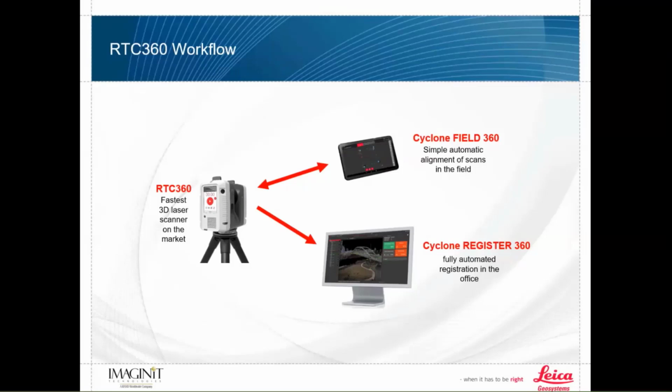From the RTC, we then would take the thumb drive out, put it into the computer, download the data to the computer, and then import that data into Cyclone Register 360. This data will only come into Cyclone Register 360 and Cyclone Register. This data will not import into the BLK edition.